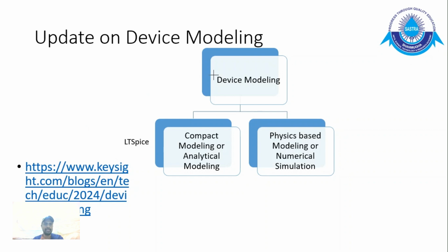I just want to show you one SPICE as well. So this is LTspice, it's free. I have taken a diode here. Whenever I take a diode, it's not the diode that is getting invoked. You guys have to remember this. What is actually getting invoked is the thing behind this graphics, the images: the model. I'll show you the model. You scroll this. So this is a SPICE model. This IS, RS are the parameters of the compact equation that's getting solved when you're using this diode symbol in the SPICE simulators. Okay, makes sense. So this is a compact model, but this is not our course.